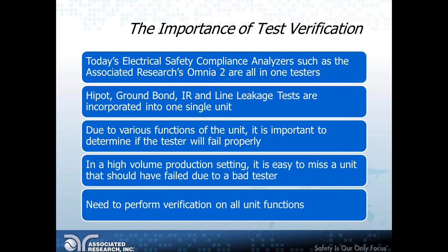And due to the various different functions of the unit, it is very important to determine if the tester will fail properly. Especially in a high volume production setting, it is very easy to miss a unit that should have failed due to a bad tester. Therefore, it is important to perform verification on all unit functions.